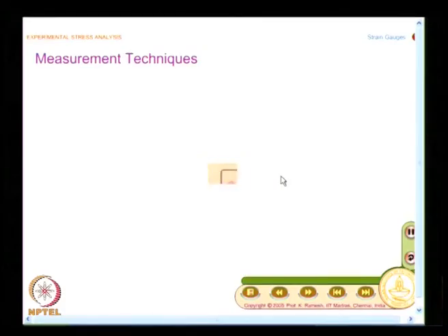See, if I have a single gauge which is self temperature compensated, I can directly read from the strain meter, the job is handled very comfortably from the measurement point of view. On the other hand, if I have to do any of this, you have to look at the graph and subtract it. With modern computerization, you have such a database available along with the software that the manufacturer supplies. So, all this is also now easy to handle with System 5000, System 7000 and so on, but the methodology is this. You should not take a wrong view that STC gauges can be used for a wide range of temperature, it is not so. But if you work beyond the range of temperature possible, the via media is to measure the temperature, use the graphs available and subtract the information. So, that makes your life a lot simpler.